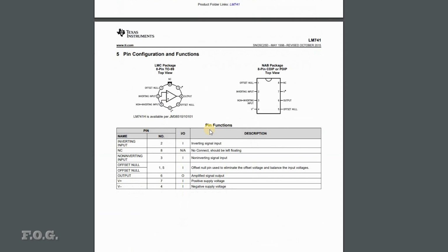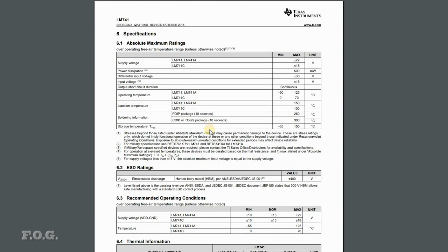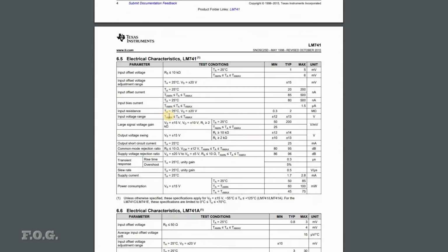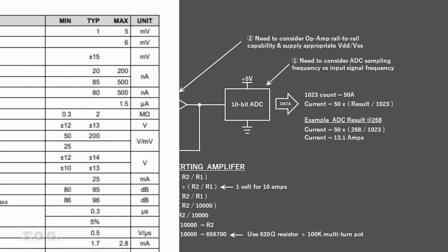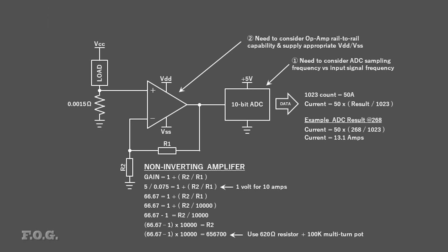Now if I remember correctly, if you're using a simple 0 to 5 volt supply, you're likely only going to see an output swing range of between 1 and 4 volts. It might even be worse than that, but I think it's something like that. This means, regardless of what the formula tells you, the actual output will be capped to be within this swing range. For our current example, that would mean only measurement results above 10 amps and below 40 amps could be considered valid, which is actually pretty terrible when you think about it.